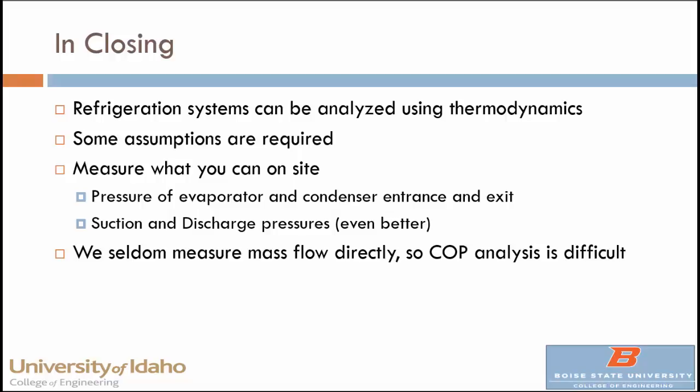Short of that, we can find the temperatures of the evaporator and condenser. And keep in mind that's the temperature at the outside of the tube. Since there's heat transfer across the tube wall, we know that there will have to be some kind of dT/dx going on there. So that's a little confusing. We have to do a little fast footwork to somehow compensate for that.